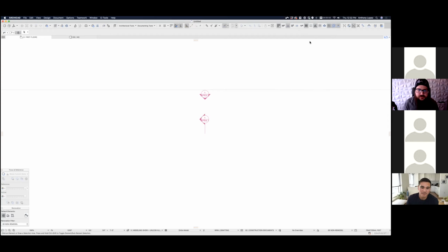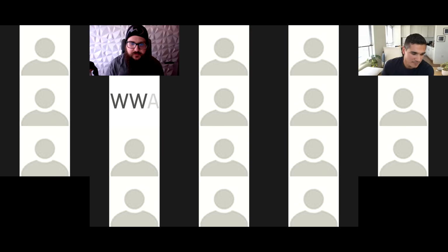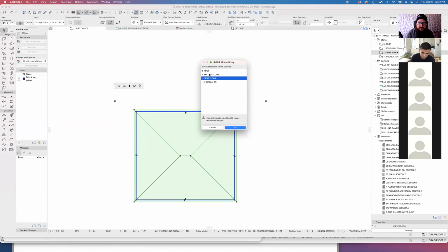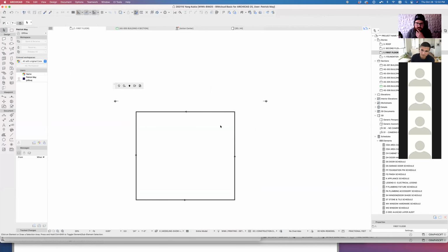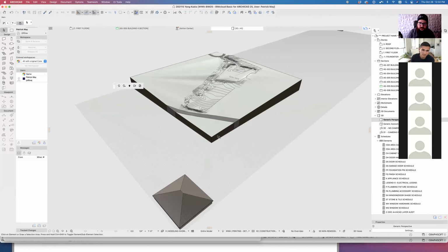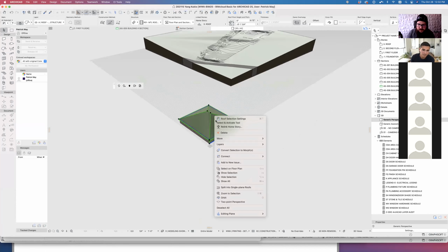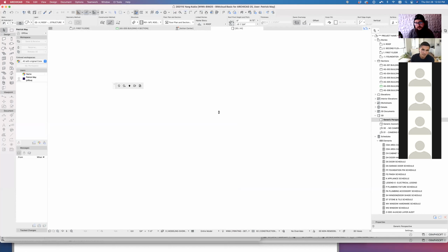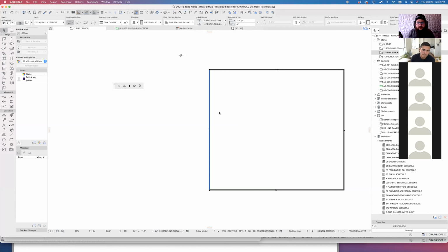Let me share my screen and just try that. I hadn't actually tried that honestly, but that's a good question. So if I move this to, let's just put that on the roof story, and then grab this and this. So the wall's on the first floor, the roof is on the roof story. So it goes to whichever story was the current tab open, apparently.